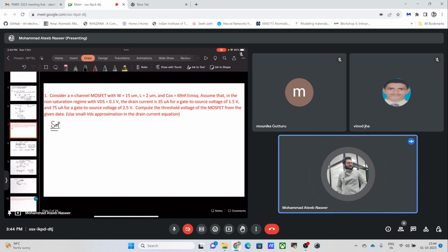So we applied the drain bias, and this drain bias attracted the electrons towards the drain. We saw how increasing the drain bias resulted in pinch off, and then the pinch off point moved into the channel towards the source region. As a result, we are now ready to deal with problems related to saturation or non-saturation regions.